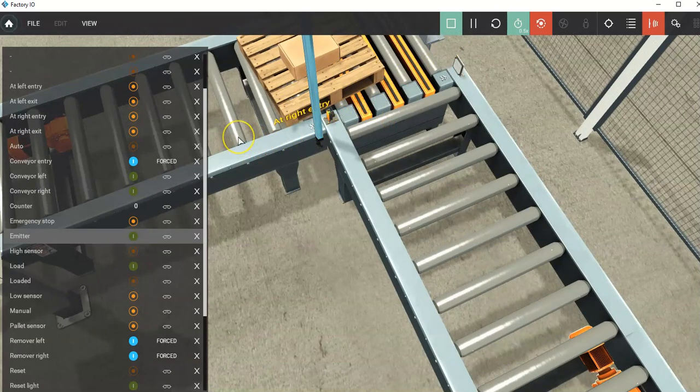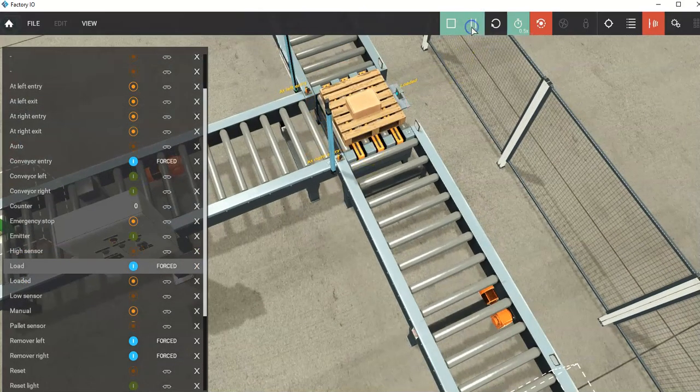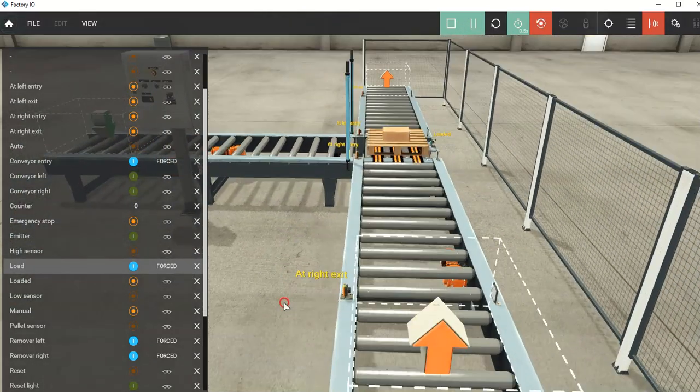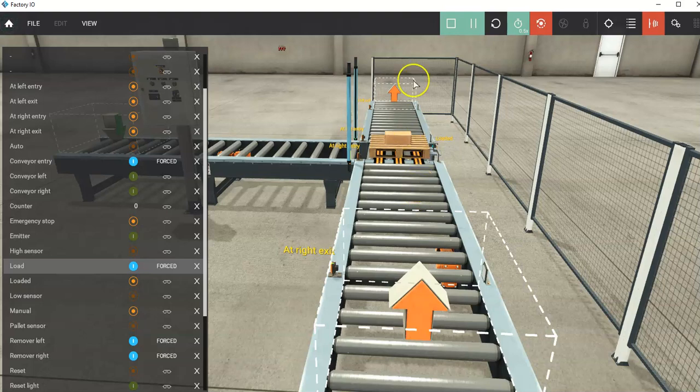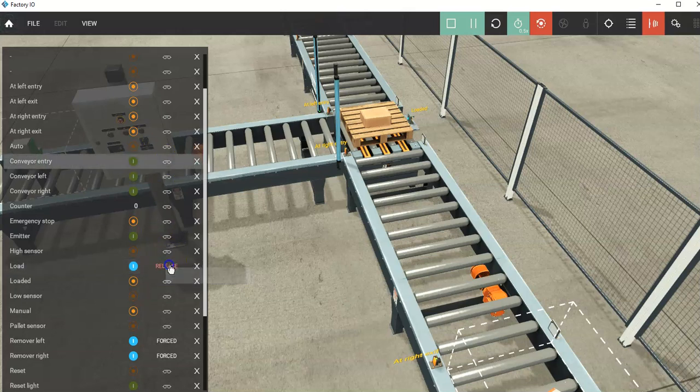You can see that this is rotating here. You can see a little tiny white dot that's rotating around, but this isn't rotating at all. So this conveyor is called the load conveyor. If I force this one on, then it'll go into position, and now I'm going to stop it again. Now it's in position where it can be transferred either up in the screen or down in the screen. At this point we can also force off all our conveyors up to this point. So we can release this one, and this one, and now hopefully we've determined that it was a low box and we've latched that in.